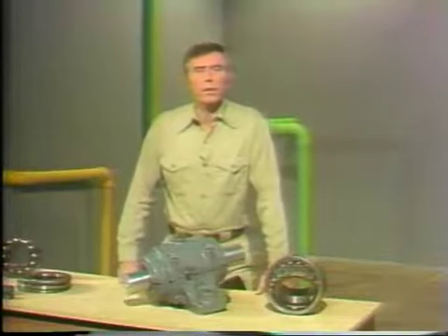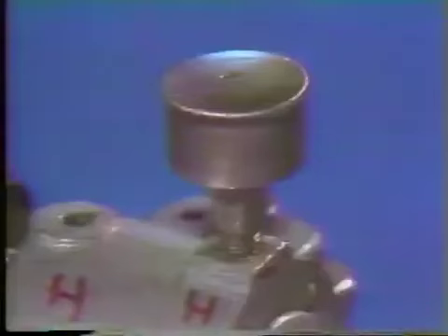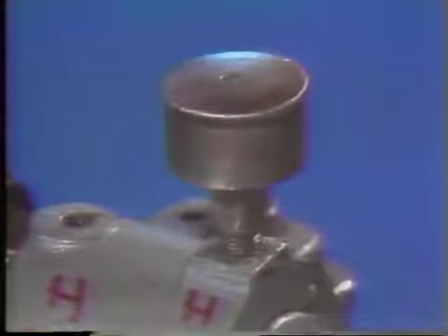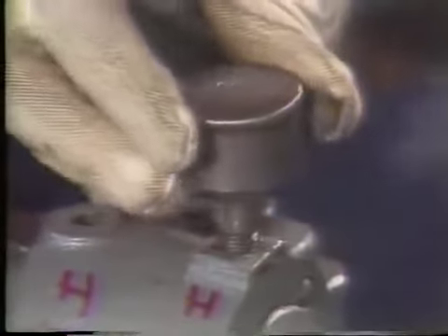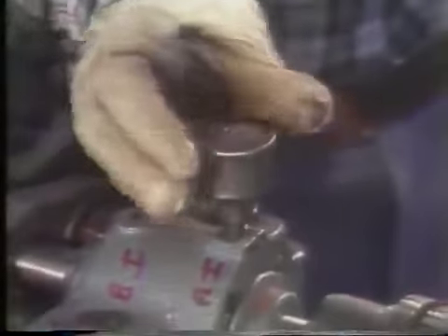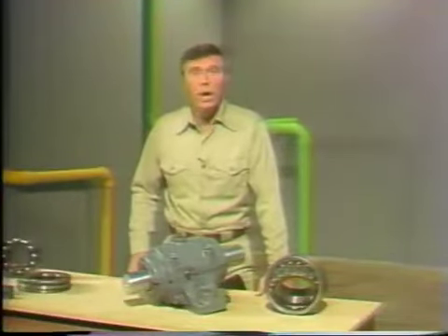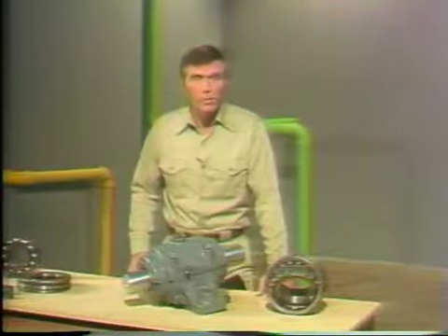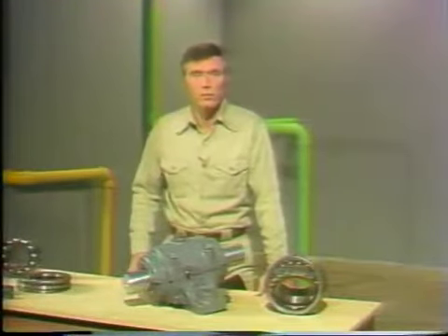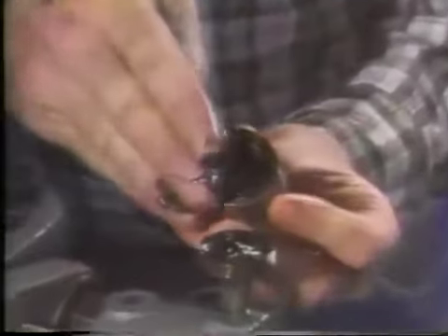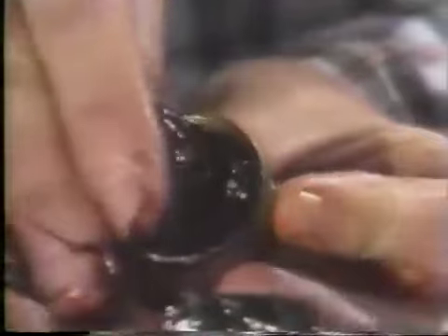Another method of greasing a bearing is to use a grease cup. A grease cup is a container with grease in it that is mounted right on the housing. To force grease into the bearing, you turn the top of the cup. Usually, 1 to 2 turns is sufficient to grease the bearings. Again, your plant may have specific guidelines concerning how much and how often a grease cup should be operated. Ask your supervisor about them before you start. Also, make sure there is enough grease in the cup before you begin. If it's nearly empty, refill it with the right type of grease.